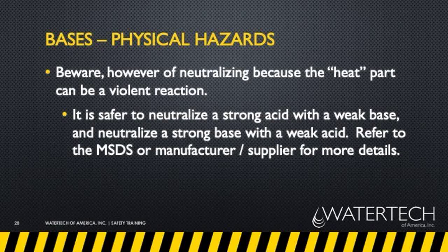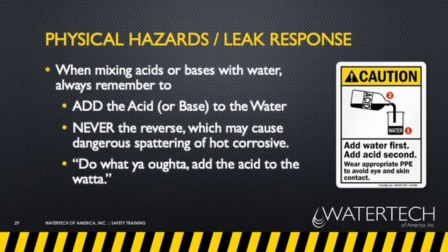We neutralize acid spills using soda ash, which is a weak base, that won't have a violent reaction. You can neutralize strong acids with weak bases and strong bases with weak acids. Never neutralize strong acids with strong bases and vice versa, or a violent reaction will occur. When mixing acids and bases in water, remember to always add the acid to the water. Don't ever do the opposite. If you add water to acid, it's going to splash and splatter. Always add RO alkaline and acidic cleaners to water, not the other way around.